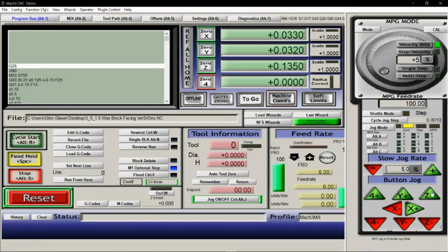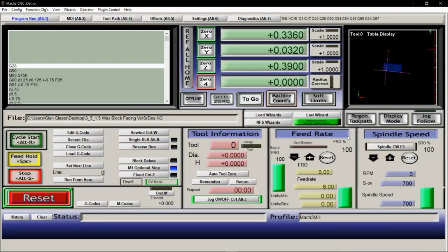As I stated, they also provide hard buttons to move the axis. As you can see, I can move the z-axis positive by pushing this, and move the x-axis in the positive direction by pushing this button here. To get rid of this window, click the Tab button again, and it will give you back the default screen.